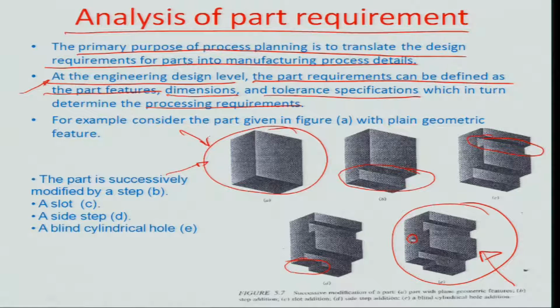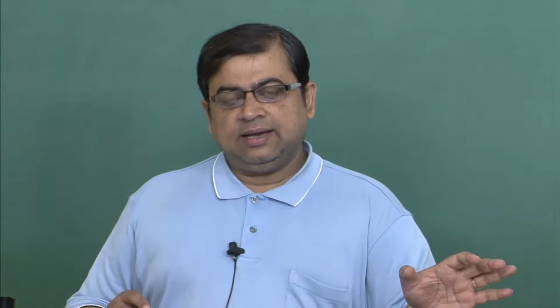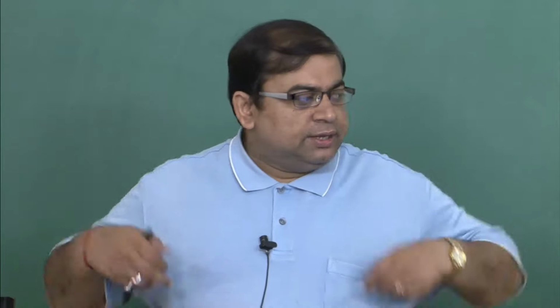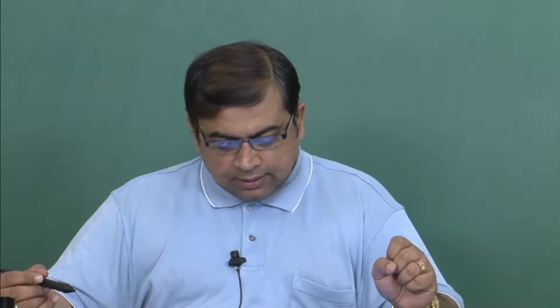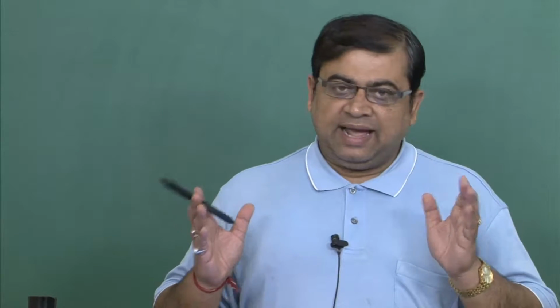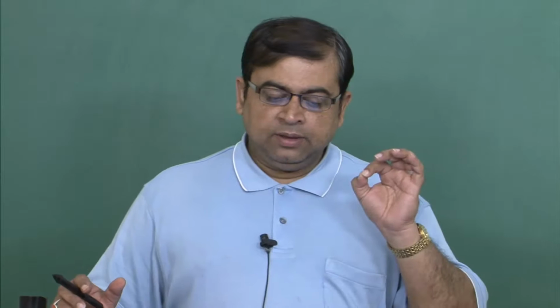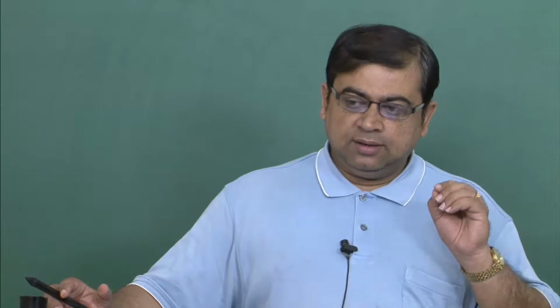So this sequence of operations, that is, what precedes what, is nothing but a sort of intelligent approach looking at the various machining concepts which have been described before, to realize the final three-dimensional geometry from the solid block of material according to the engineering requirement. In this analysis of the engineering design requirement, obviously there has to be a feature size, a tolerance size, a basic dimension, and a process capability.